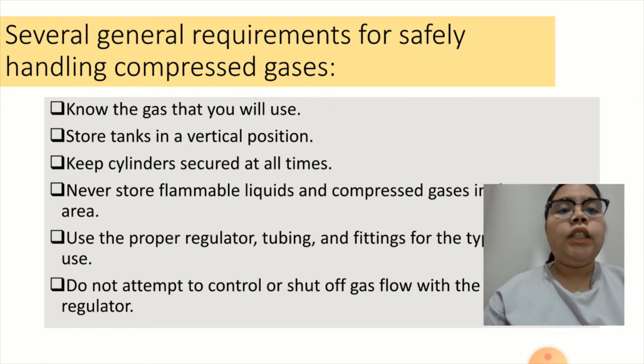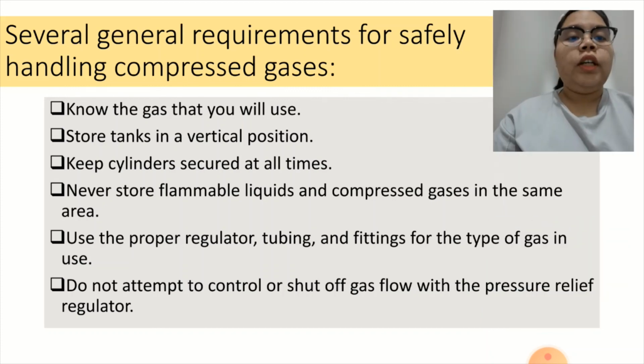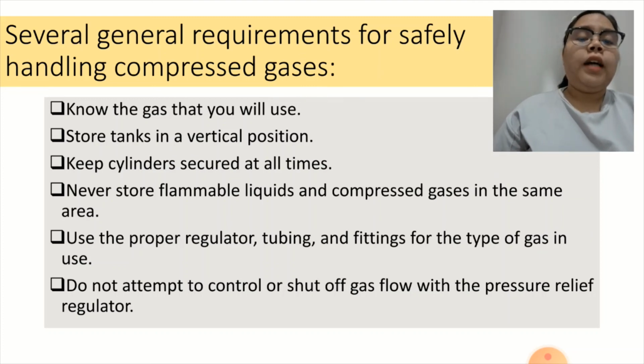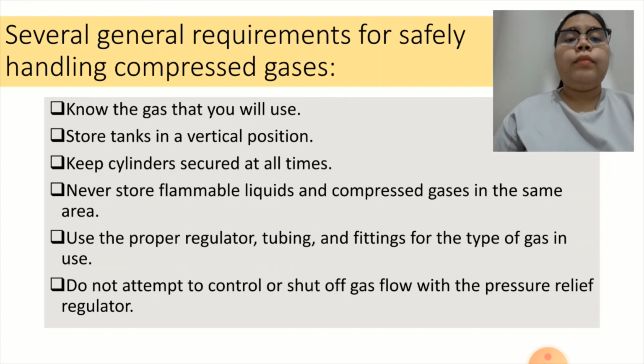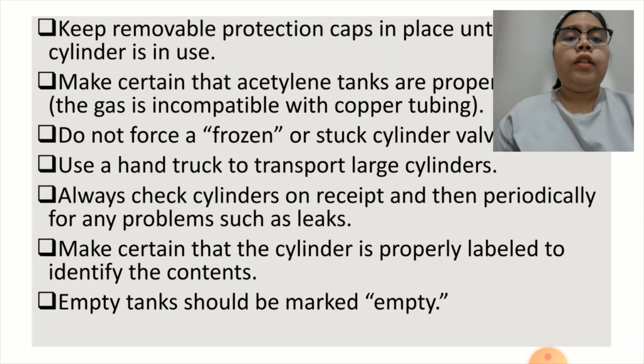Keep cylinders secured at all times. Never store flammable liquid and compressed gas in the same area. Use the proper regulator, tubing, and fitting for the type of gas in use. Do not attempt to control or shut off gas flow with the pressure relief regulator, and so on and so forth.